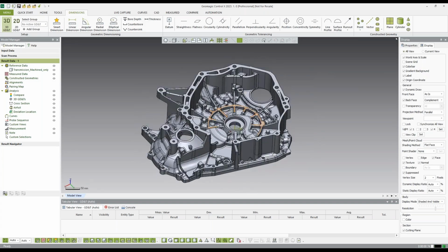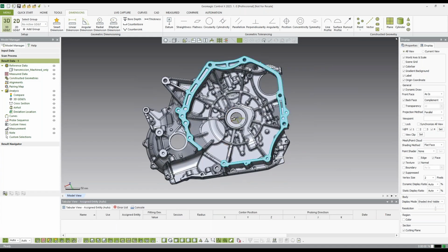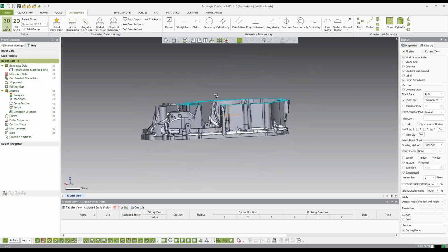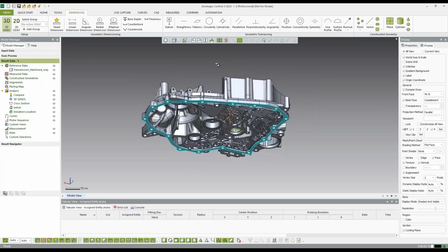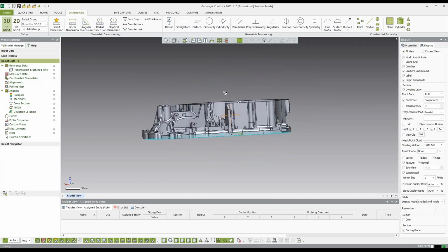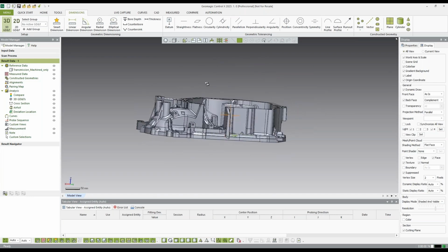And then I usually pick which dim groups I'd want to show datums in, okay? Because if I'm looking at this front face here, on a print you would never see this from the top. You would always see it from the side. And same with the back face. If this is a mating sealing datum here, you would see this on the side view. So I try to think about that as I lay stuff out.